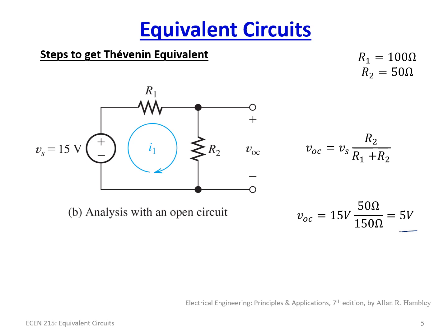So what do we need to create a Thevenin equivalent? We need the open circuit voltage from here, which gives us our VT is equal to 5 volts. So that's it. Half of the battle is won here. We have two steps. We have to get the Thevenin equivalent voltage, which is the open circuit voltage across the terminals we're interested in, and then what is known as the Thevenin equivalent resistance. And there are actually two ways to do that. So we're going to show both methods.